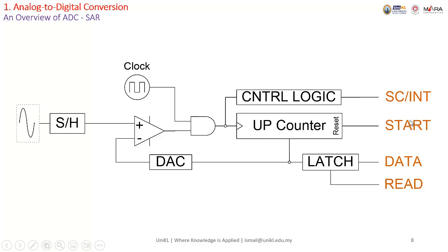So when we click start, over here we already preload that 76, and then say the input is about 1.6. The voltage here is about 1.5, here 1.6. So it takes about 0.1 volt to up the counter. So it takes less time.